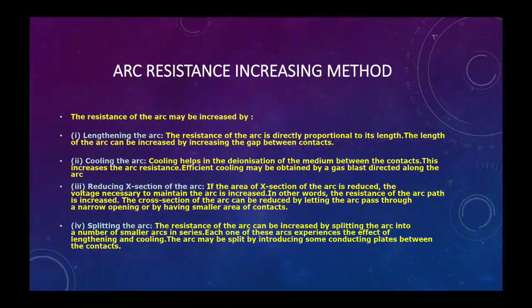The arc resistance increasing methods are as follows. Number 1, lengthening the arc. The resistance of the arc is directly proportional to its length. So the length of the arc can be increased by increasing the gap between the contacts.